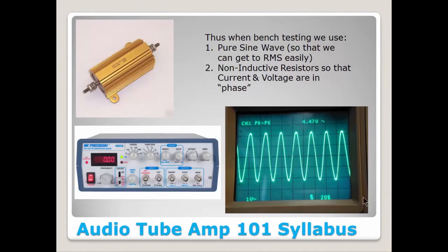And then you just need a basic oscilloscope. Now, I will tell you, not all oscilloscopes display this. Like this one is set on channel 1. It is reading the peak-to-peak voltage at 4.47 volts. Or you could set it to read the peak voltage here, and it would tell you that. Not all oscilloscopes do that. The further back in time you get, they don't have a digital display like this. Some of the newer modern ones will have these displays. So you can get a $300 Rigol oscilloscope, pretty modern one, and it'll display all this for you. So not a ton of investment.